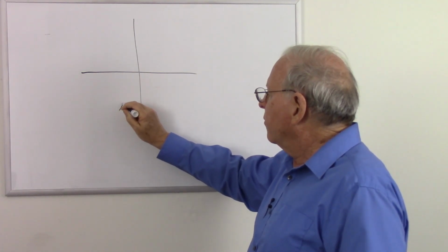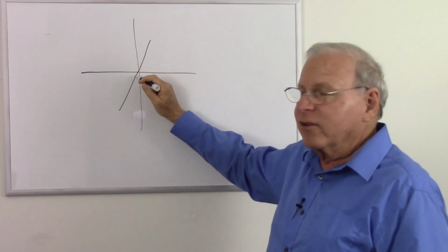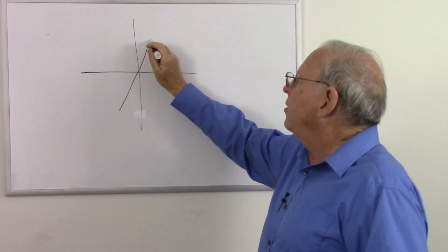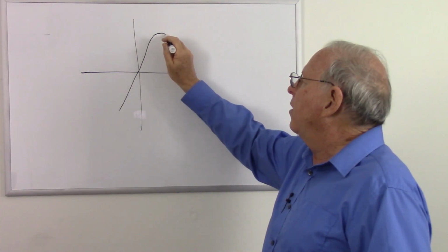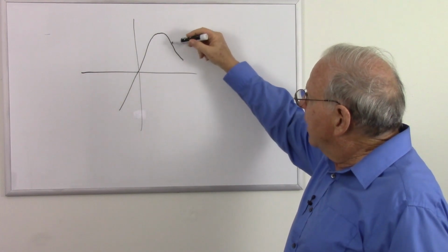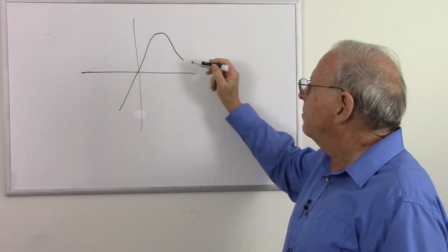So here is our reverse bias region crossing the 0 point. Pretend that's going right across the 0 voltage and 0 amps point there. It reaches a maximum current and then heals over, and then as we increase our voltage, we get less current. So now here I increase my voltage, current goes down. Decrease my voltage, current goes up.